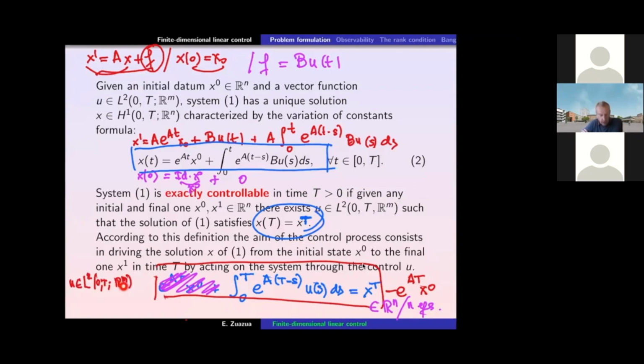So you see, there is only one control or m controls. M can be very small, it's finite. But I have the free choice of the control for every time instant. So what is the dimension of that space? We say there are n equations, and I am allowed to choose u as I want in order to fulfill these linear n equations. What is the dimension of the space u that I have at my disposal to do it?